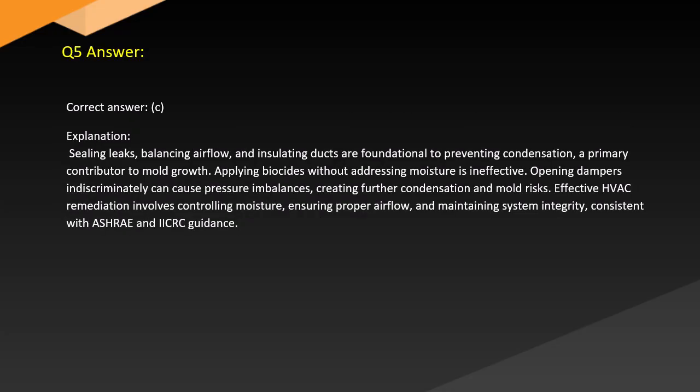Answer. Correct answer: C. Explanation. Sealing leaks, balancing airflow, and insulating ducts are foundational to preventing condensation, a primary contributor to mold growth. Applying biocides without addressing moisture is ineffective. Opening dampers indiscriminately can cause pressure imbalances, creating further condensation and mold risks.